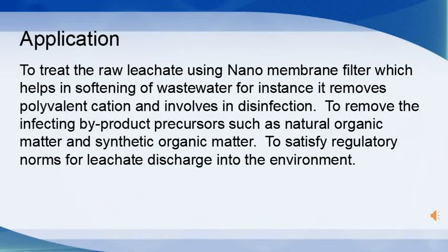I am Amirul. I would like to talk about the application of nanofiltration, which is used to treat the raw leachate using a nanomembrane filter, which helps in softening of wastewater. For instance, it removes polyvalent cations and is involved in disinfection, to remove the disinfection by-product precursors such as natural organic matter and synthetic organic matter, to satisfy regulatory norms for leachate discharge into the environment.